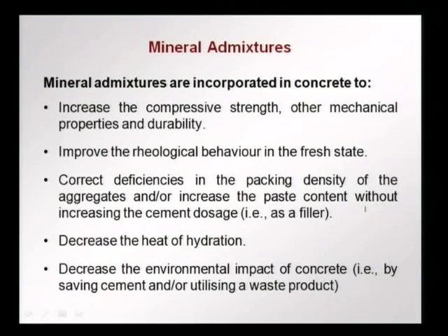In addition to the aggregates, cement and water, nowadays we use mineral admixtures incorporated in the concrete. This concept started off in the 1970s, when people found that mineral admixtures, when added to concrete, increase the compressive strength, other mechanical properties, and very importantly the durability of the concrete. The concrete could last longer when certain mineral admixtures, fine materials, were incorporated into the concrete to supplement, to complement the role of the cement in the concrete.